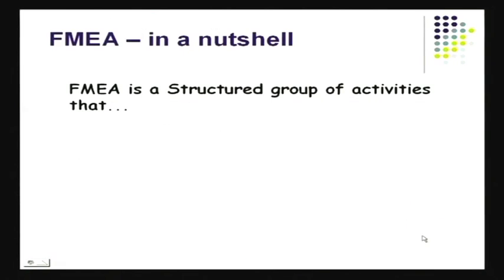And of course, in addition, you'll also end up with some priorities, because you could do many different things. And the FMEA approach also gives you a sorting of priorities. It tells you what are the things that you must take some steps to try to prevent now, try to take some corrective action now. What are the other things that could probably wait, and you'd probably take some time to figure those things out and probably take some corrective action. But the ones that have high likelihood of failure and also have a high impact, those actually are the ones that should be addressed as quickly as you can.